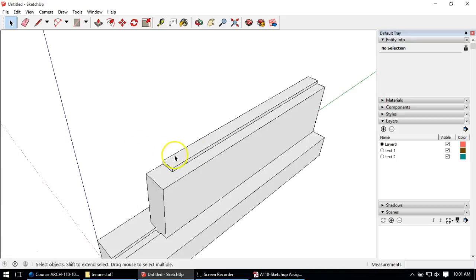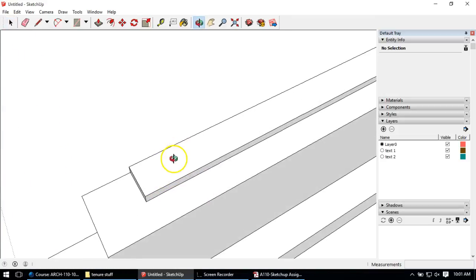So I'm going to start with the bolt. To do that, I'm going to go to this icon here to get to my shapes, and I'm going to go to my polygon down here, and the shape of this bolt has 1, 2, 3, 4, 5, 6 sides. We can see down in this right hand corner mine already says 6, so I'm going to assume that's the default.